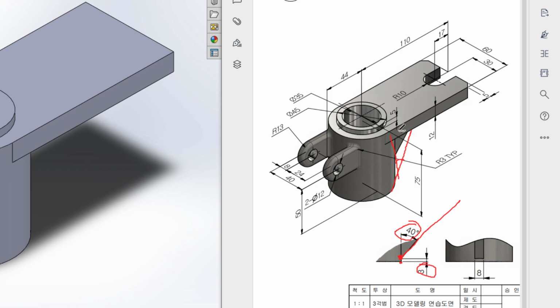Here you can see this is a circular shape, so that's why I will extend this line a little more here. Then I will draw this triangular shape. I will extend this line further, because it is a circular shape. When I extrude it to 80 unit, if I don't extend this line, I will miss some edge here and here. That's why I will extend this line further away from this point.